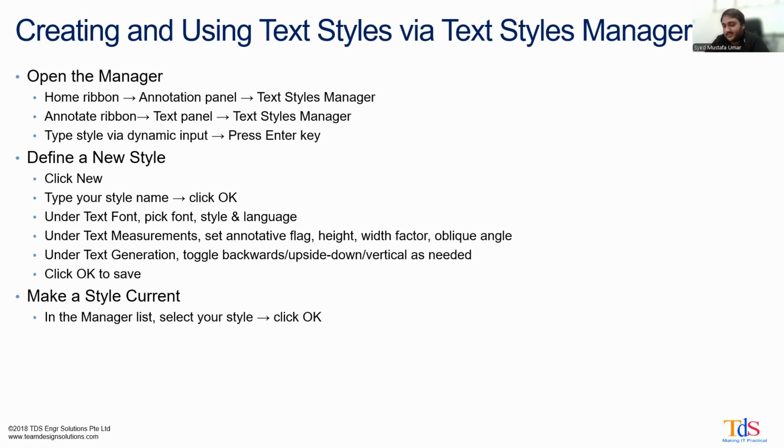There's going to be a specific pattern that we follow for each of the styles of text that we're talking about. So even if we're talking about regular text, multi-line text, dimensions, or multi-leaders, there's always going to be a specific format that we follow. But first, we're going to discuss how we define a new style, and where the manager, the explorer, for that certain style is. So right now we look at the text style manager or the text style explorer, depending on what your preference is. What kind of UI are you more comfortable with?